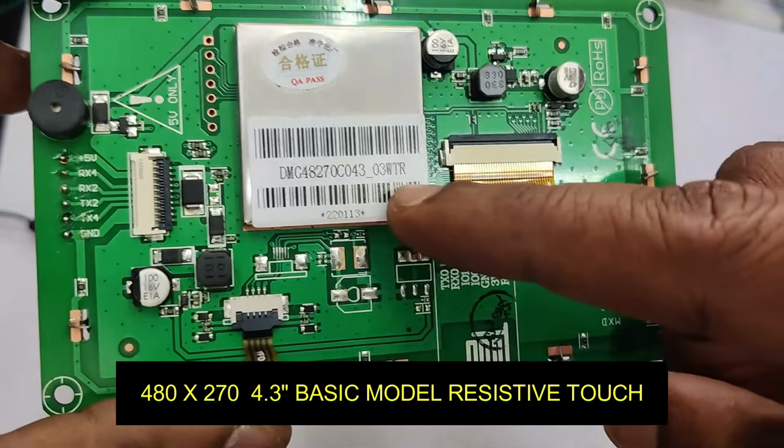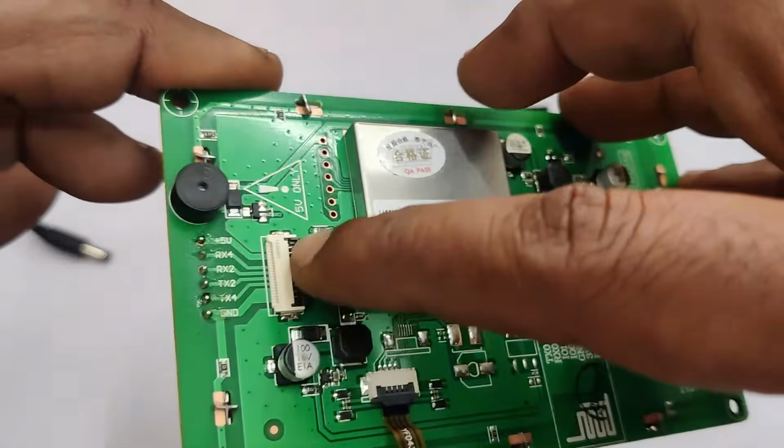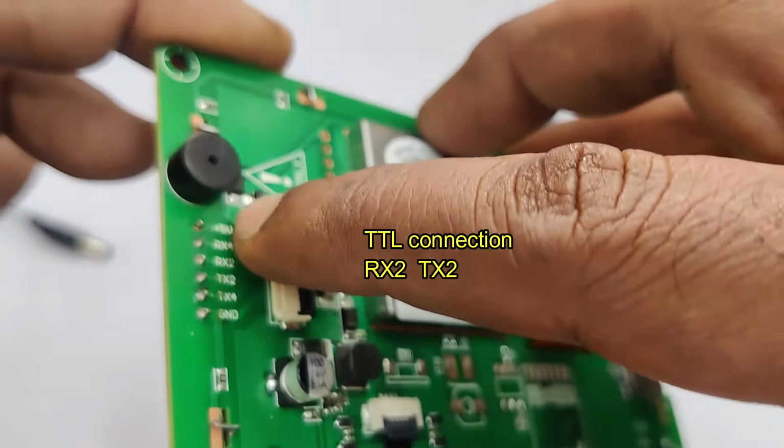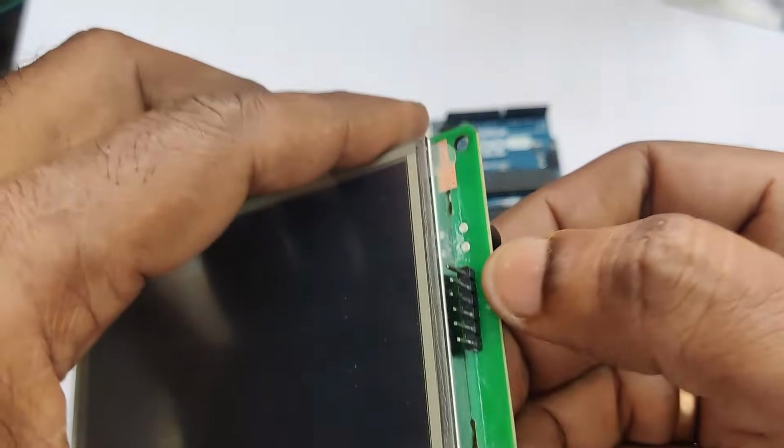In this demo we have got 4.3-inch basic model resistive touch display with a resolution 480 by 270. This is very economical and effective. It has got TTL connections. We will be using RX2 and TX2 to connect with the Arduino. We have to solder these pins.